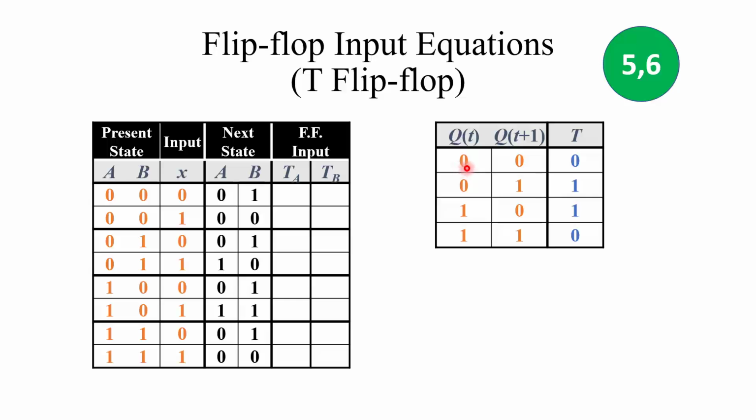If we look at the first state transition, 0 to 0, it is the no change case, because we know from the characteristic equation of T type flip flops that it only has two particular states, either no change or toggle or complement state. So 0 to 0 transition can only occur when the input T is 0 and no change has occurred.